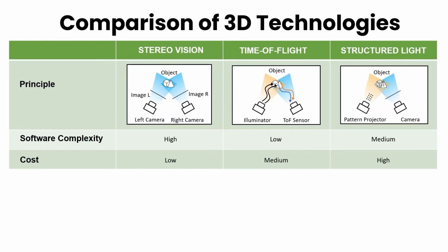When it comes to cost, stereo cameras tend to be cheaper because they are built using CMOS sensors. Among the three, structured light is the most expensive. In general, time of flight cameras are cheaper than structured light systems, making them a viable option for a lot of depth-based embedded vision applications. Let us now look at how these technologies differ with respect to accuracy.